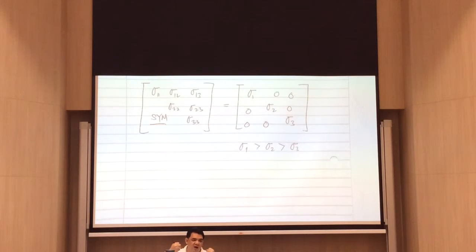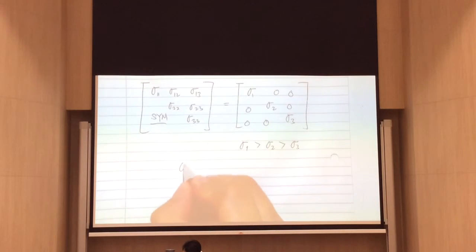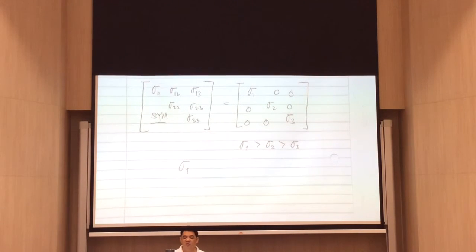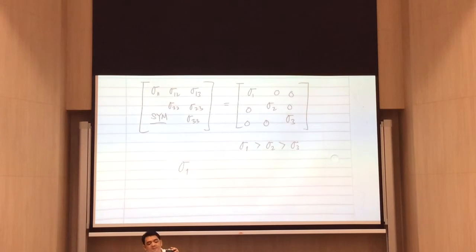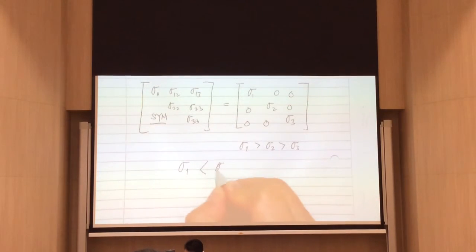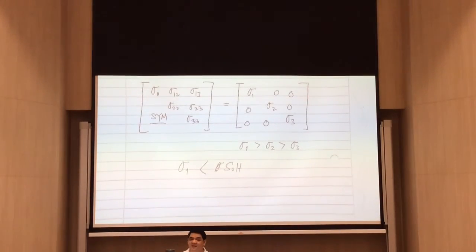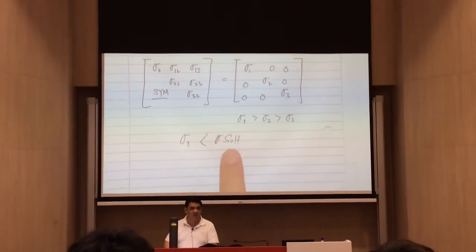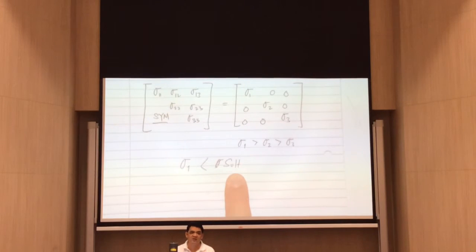And to which value do we compare this one? The ultimate strength of your material. So as you can see, that stress acting on your material must be less than the strength of this material, yes? Otherwise, it will fail. So, for this to be safe, it must be less than that ultimate strength. This is a material property, taken from tests.